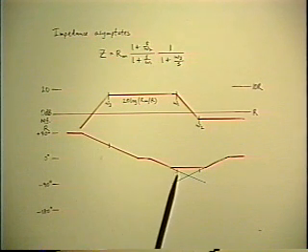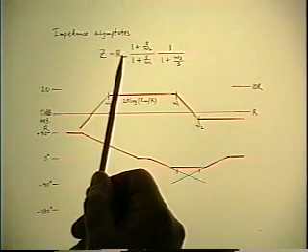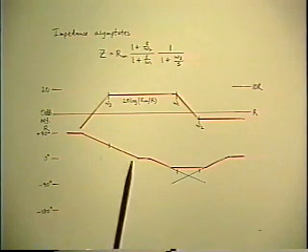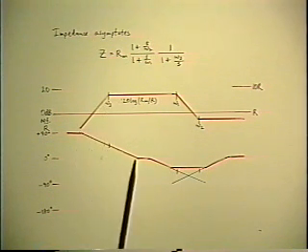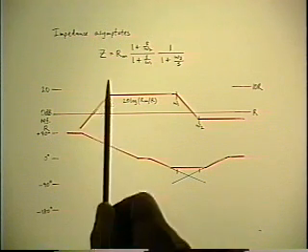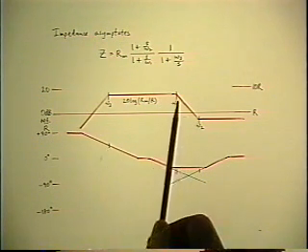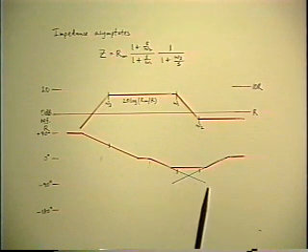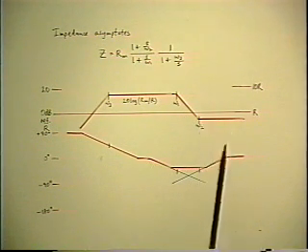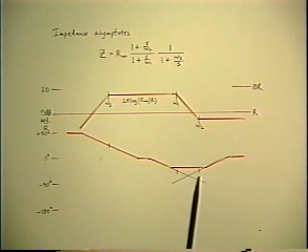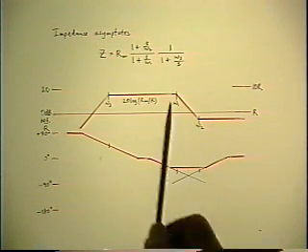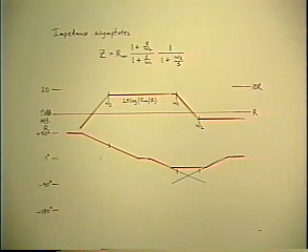The phase graph, of course, is completely unaltered because that's independent of what the coefficient in front is anyway. That's only a property of the poles and zeros. So in this particular example, the inverted pole has a negative phase slope, minus 45 per decade, centered on the pole. And then a normal pole also has a minus 45 per decade. And the zero will bring it back to 0 degrees again eventually. I drew the case where there's a substantial overlap, but it may not, depending, of course, on the relative values of those two corner frequencies.